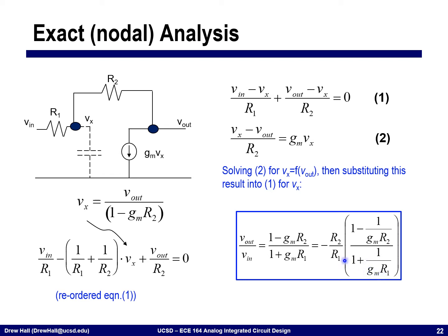Okay. This is the closed loop gain of this amplifier, and this term over here, we're going to see in just a second, is the loop gain. So the loop gain is equal to GM times R, and if we have high loop gain, we can show that this particular portion of the equation will cancel out. All right, so if we did have GM R much greater than 1, this would exactly agree with the op-amp solution that we were just describing.